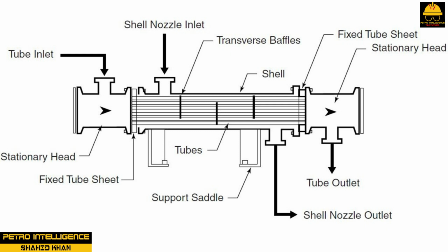As flow enters the tubes, it experiences maximum heat transfer. Conductive heat transfer is at its highest where the tube sheet, shell, and tubes meet. By the time the tube flow exits the exchanger, very little, if any, heat transfer is taking place. The term single pass indicates that the tube side flow goes across the exchanger one time.